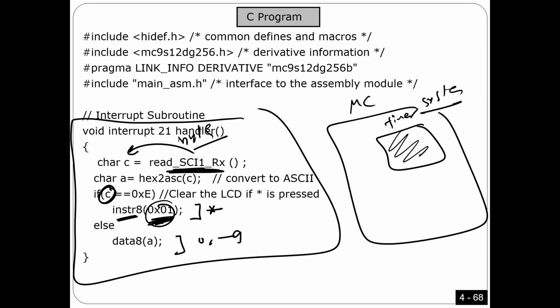We are going to take very little time from the microcontroller. This is the key, this is what we should learn in this course. Because of interrupts, most of the work is going to be done by the timer system. If you wanted the timer system's functionality using the CPU, it would take too much time. But the beauty here is that most of the work is done by the external circuit. That's why you can make big applications, as you will understand now.